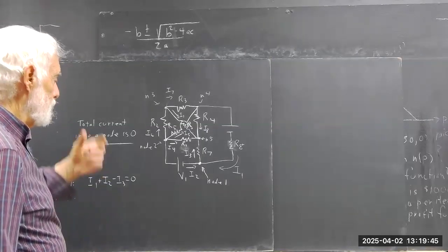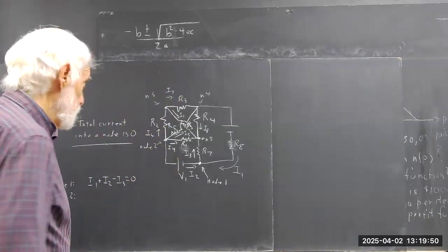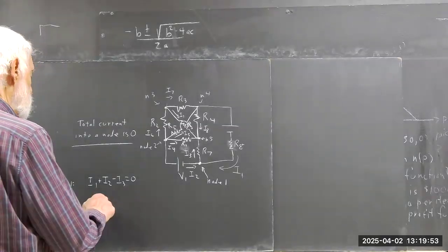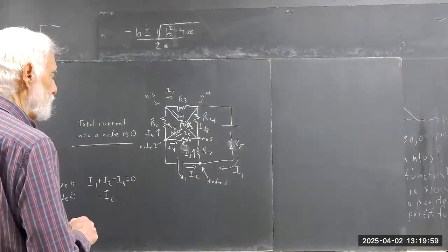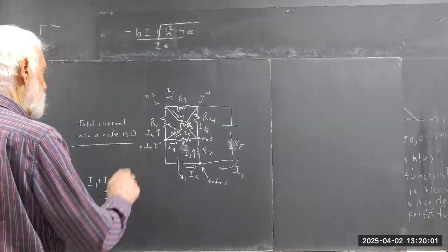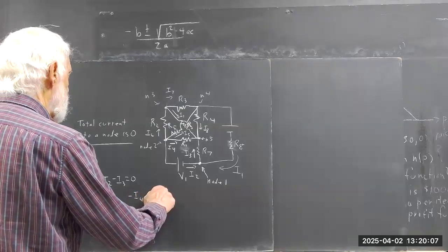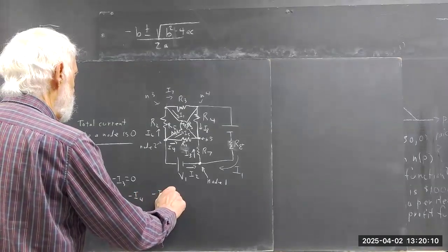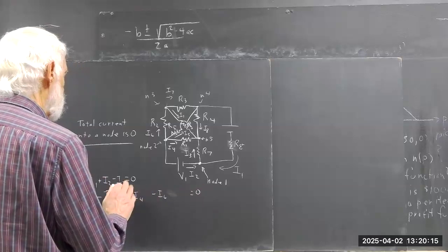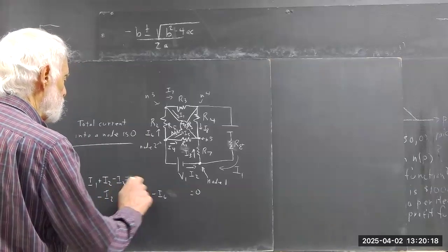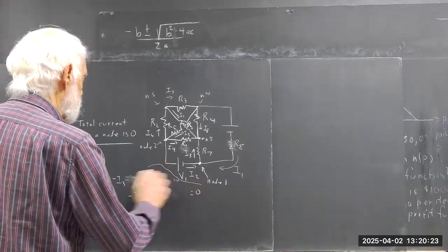So we're going to say, it actually looks to me like all of these currents are going out of the node. So if I want to write this carefully, I would start lining these up. I'd write minus I2, and then I'd have minus I4 and minus I6 here, and that would equal, then I'd leave myself room for I7 and I8, and I'd put equal 0 over here. And then I'd rewrite my equal 0 and move it way over. I don't have room to write it out there.